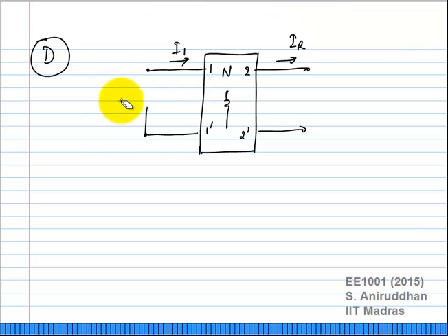So I am shorting Vs, so this just becomes a short circuit. So IR times delta R, and this current of course is only delta I1. Okay, it's no longer I1. It was I1 plus delta I1. When I apply Vs only, there is an I1 current that flows.